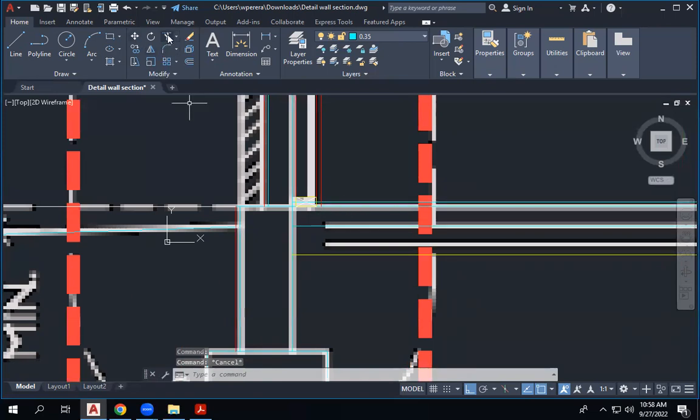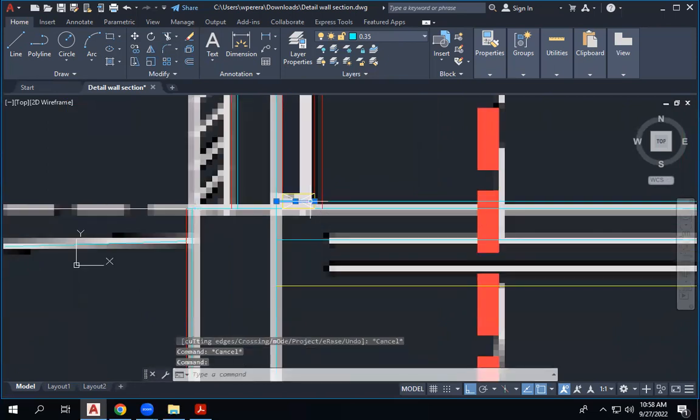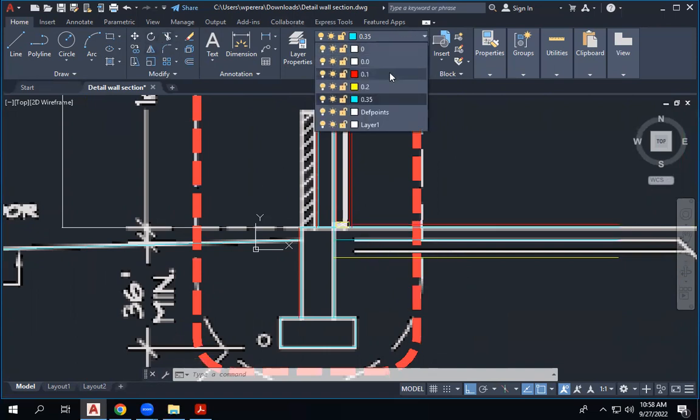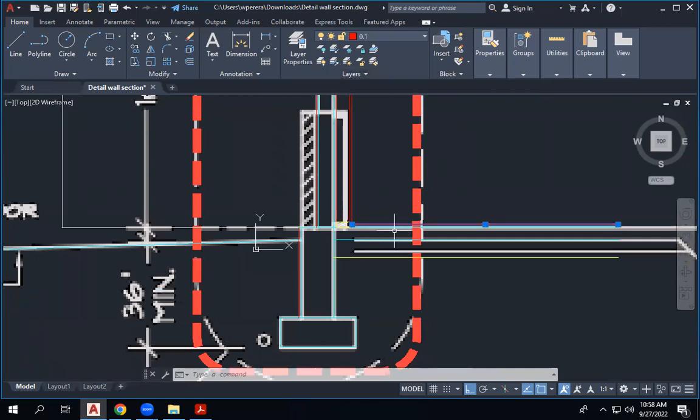I'm going to trim it here. So the tile layer will be stopping at this point. You're trimming it in the yellow timber thing. Yeah. Set distance, 1 inch. Okay. And make that line also 0.1, because otherwise there will be 0.2, 0.35 lines closer to each other. It will be totally black.